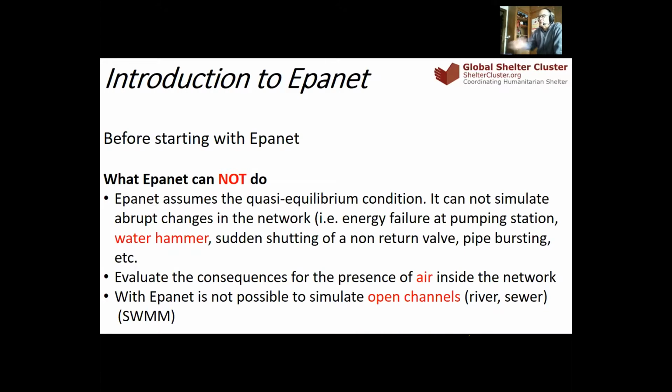And also, it cannot tell you how this network behaves if you suddenly change the water demand. That's why, for time behavior of the network, we will have to create a time pattern. This is the topic of next week.